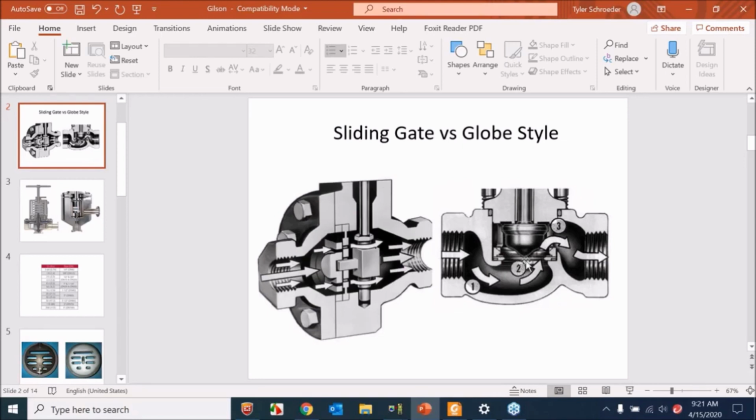Because it's going to go open, close, open, close, open, close, just trying to modulate it 3%, 5%, 10% open. So the valve's going to wear out prematurely versus operating well off the seat in that 30 to 70% control range. So you'll get premature wear if we oversize a valve and the valve just beats itself to death.